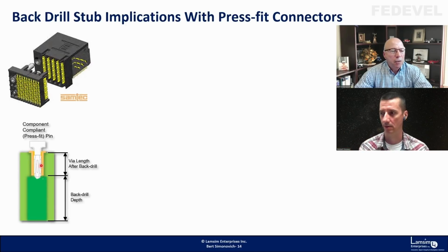Yeah, for high speed they're short, but they do need a minimum via barrel length for reliability and to make proper contact. Every connector manufacturer has their own pin style. They all work pretty much the same, but they all specify the minimum via length that you need. And if you have to back drill for high speed, you have to make sure you have that via length left.